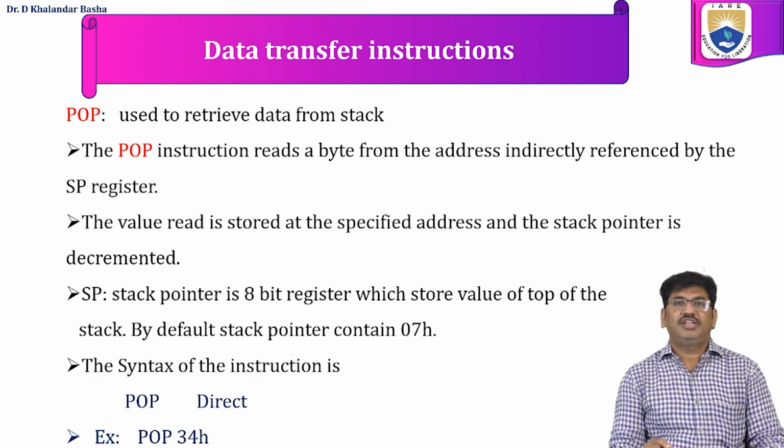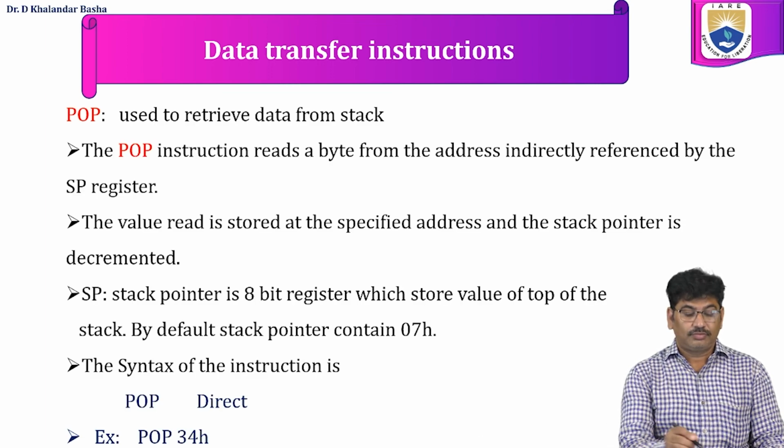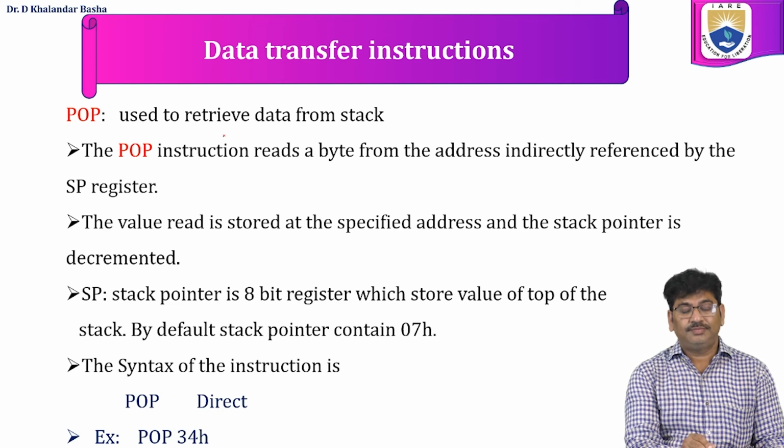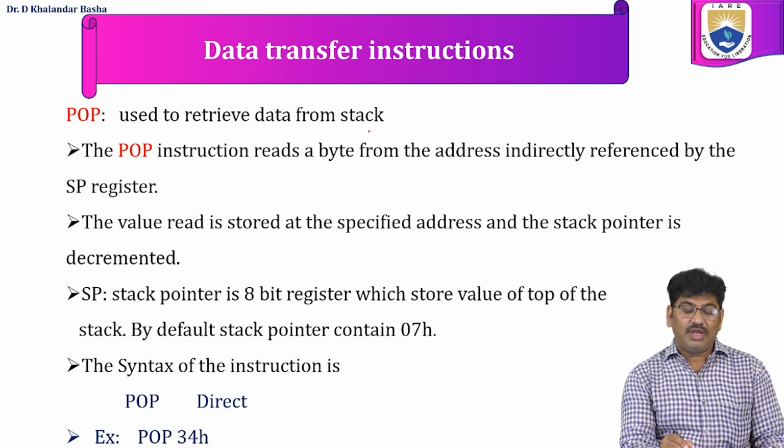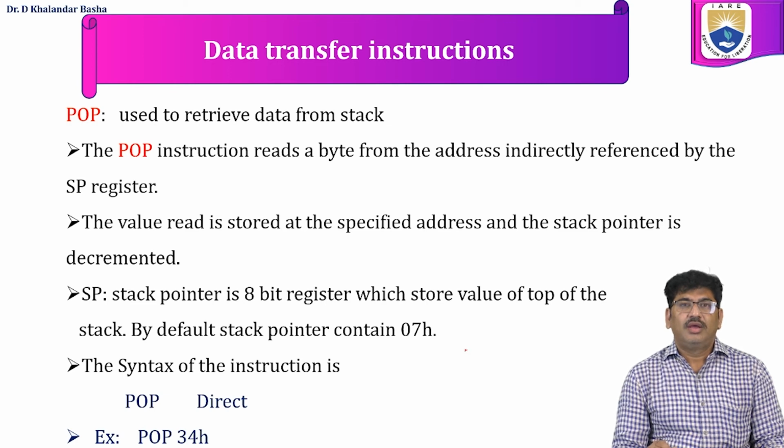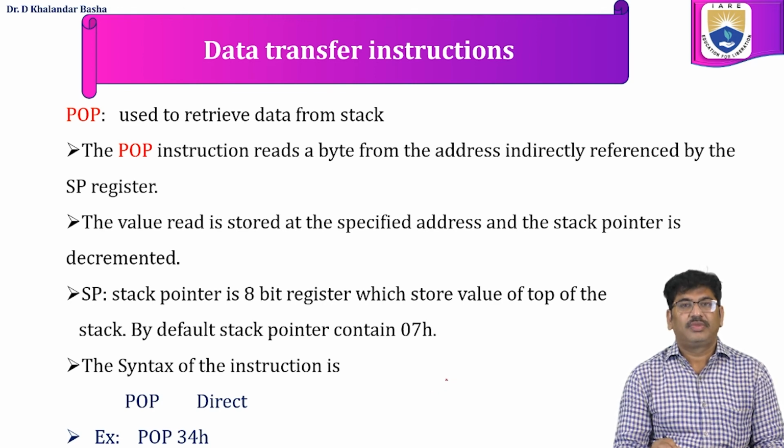The next instruction is the pop instruction. This instruction is used to retrieve data from the stack. The pop instruction reads a byte from the address indirectly specified in the SP register. The value read is stored at the specified address and the stack pointer is decremented.